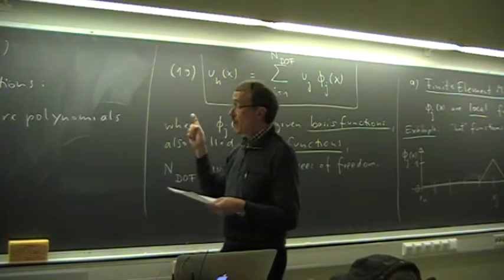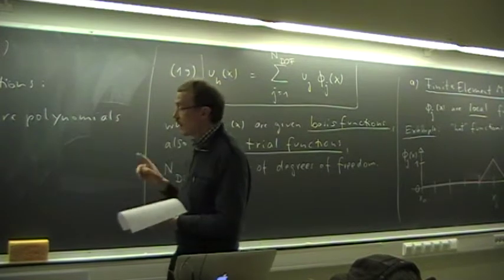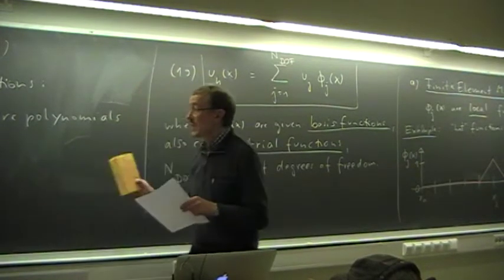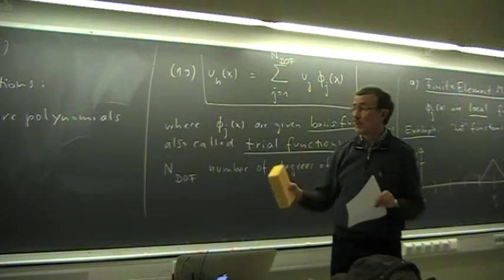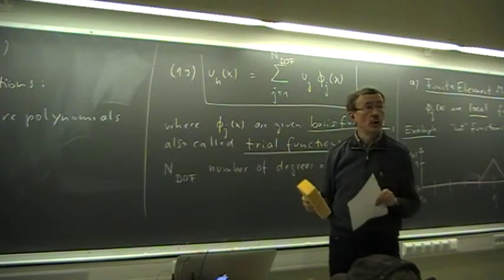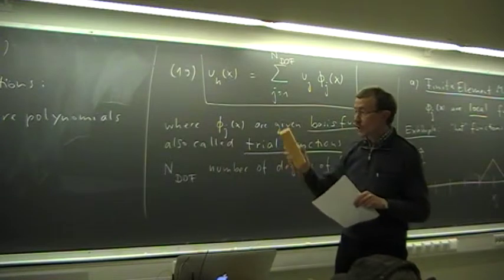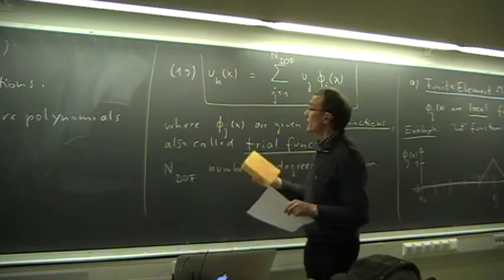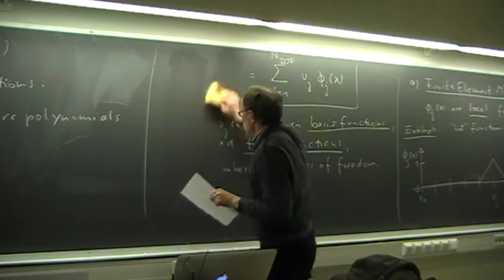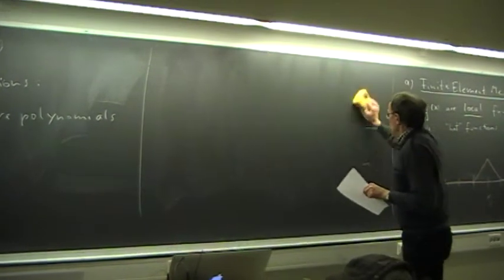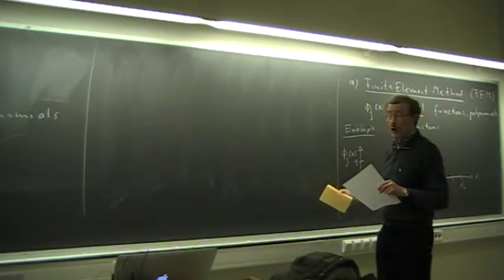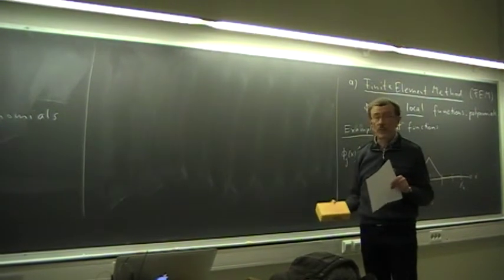So these methods are extremely accurate, but they are limited to very simple geometries and simple boundary conditions. For example, the Fourier method you can only use for periodic boundary conditions. Chebyshev is more flexible, and also Legendre. But that is the limitation of these spectral methods regarding the complexity of the geometry and boundary conditions.